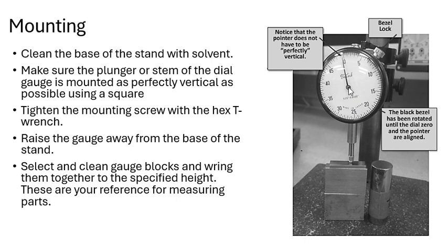Then select and clean your gauge blocks, and ring them all together so they're perfectly stuck to each other to the specific height. And these are your reference for measuring parts. I would say this mounting should come before the measurement, but I don't know why they're putting it here.